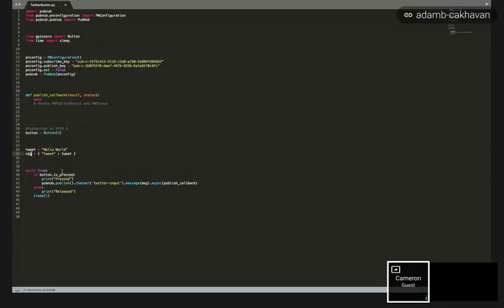And then when you want to make any program in IoT run continuously, just indefinitely, you want to make a while statement. This is called a while loop. And this is actually called polling in IoT. And that just means that it's going to be constantly checking your IoT sensors at whatever frequency the Raspberry Pi is set at. It's just going to keep running this while loop over and over again until your button is pressed. And that's what these if statements are. It has conditions. So if the button is pressed, you're going to let the terminal screen see that you pressed it. And then with the Pubnub Twitter API, you're going to publish to the Twitter API block.